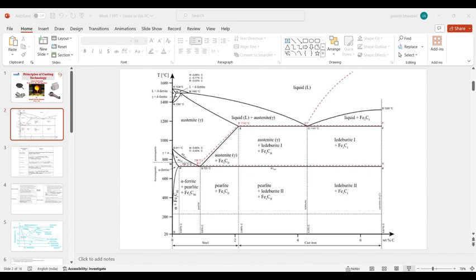After that heat treatment, we can go with any type of cooling process, normalizing or annealing, whatever we want. But we can't go with quenching because we have already done that. So that is known as the tempering heat treatment process. Coming to the next one, the spheroidizing process.